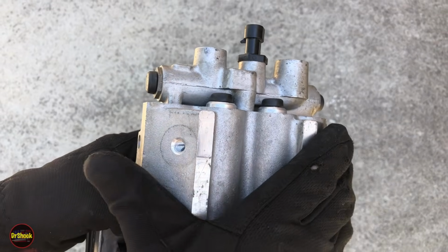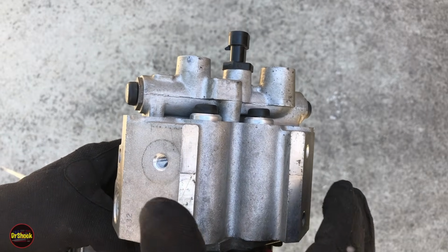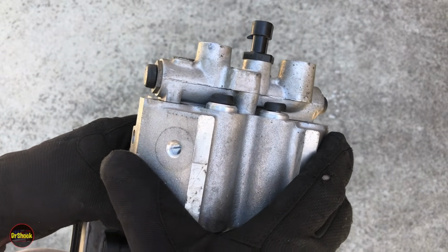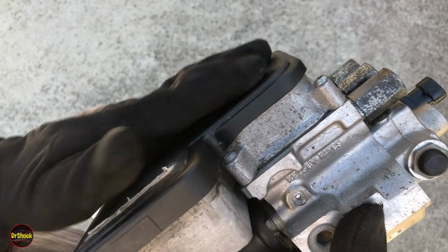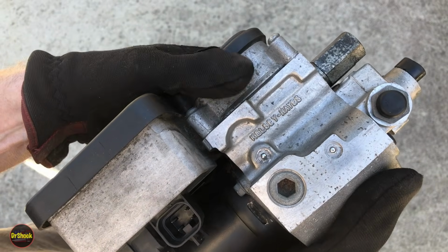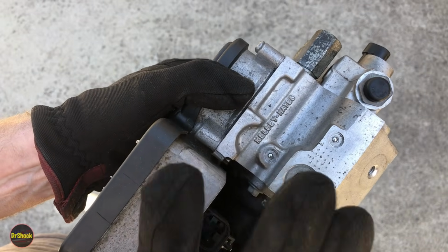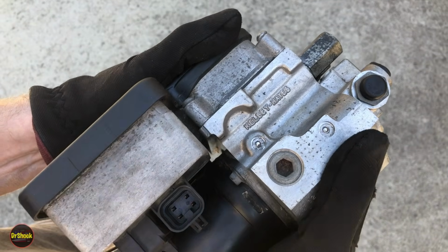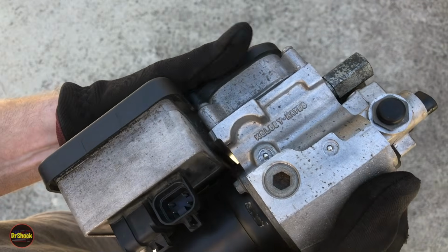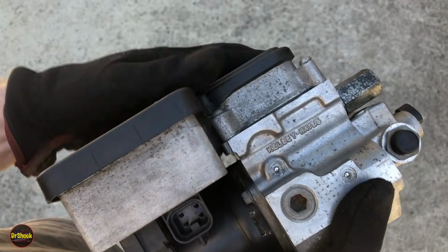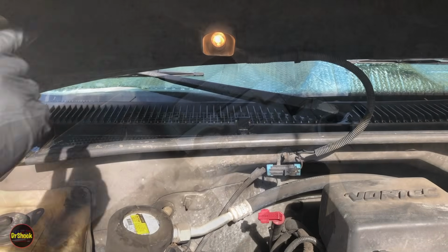So I put up with that pull that I showed you for a while, because this is an expensive part to replace normally, and it's discontinued and difficult to track down. But when the top piece failed that we just went through diagnosing, I decided let's go ahead and tackle both at the same time. And I'm quite confident that when we replace this piece along with this piece, and we basically put a whole new EHBU, electro-hydraulic braking unit, on here, then we're going to knock out both problems. So let's go find out if that's the case. All right, folks, we're going to be under the hood for a while.